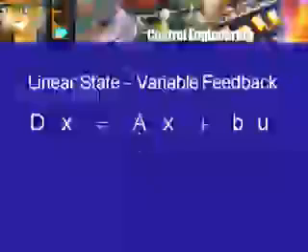of A. So, suppose that this set of equations is the set of equations for a control system, and my matrix A is such that the characteristic values are not good enough. You remember time constants that we talk about, the characteristic values or eigenvalues are ultimately related to the time constant. So, let us say that the system time constants were too slow, one or more of the time constants were rather large. So, you would like to change or reduce the time constant, so that the system response due to initial conditions only goes to 0 as fast as possible, or faster than it was doing earlier. For this purpose we want to use feedback.